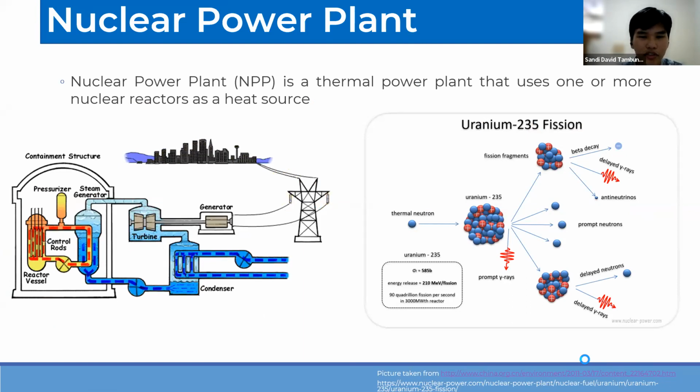Instead of burning fossil fuel, a reactor will heat water by bringing pellets of uranium close together until they form a critical mass. When uranium decays, neutrons and heat are released. If enough uranium is nearby, then the neutrons will run into other uranium atoms, causing them to split apart, or fission, and release more neutrons and more heat. Nuclear reactors submerge the fissioning uranium in water. The fuel heats up the water and the water boils and turns to high pressure steam, which turns the turbine.